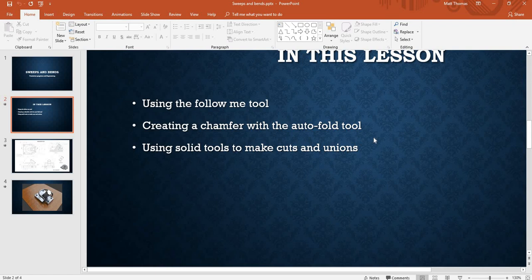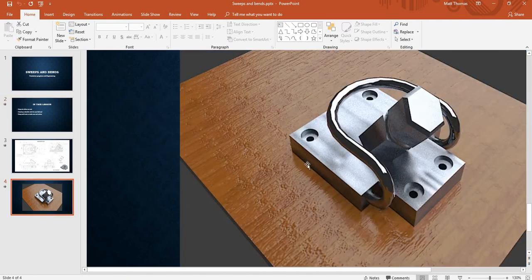I totally forgot that once that was in place inside the model, usually triple click would highlight everything, but we got lucky this time and it was able to separate that geometry for us. So if that wouldn't have worked, we could have just intersected the faces with context and then gone inside and erased the bits of the path we didn't want on the inside, and would have been able to union the model just fine.